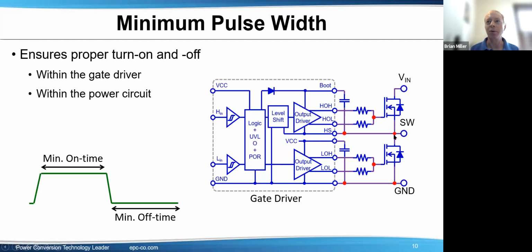A more subtle form is if the bottom gate is on for a very, very short time with a very high duty cycle for the top. You need to ensure there's enough time for the capacitor to reliably charge. So minimum off time is important for that type. With frequency, you can adjust the capacitor to make sure there's enough capacitance to hold for the whole on time.